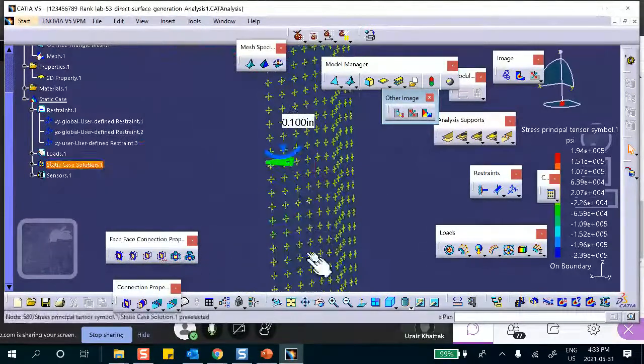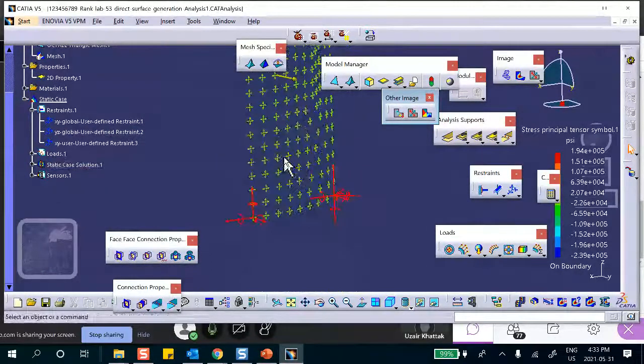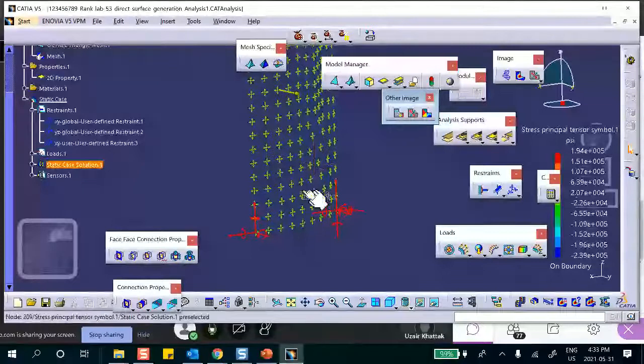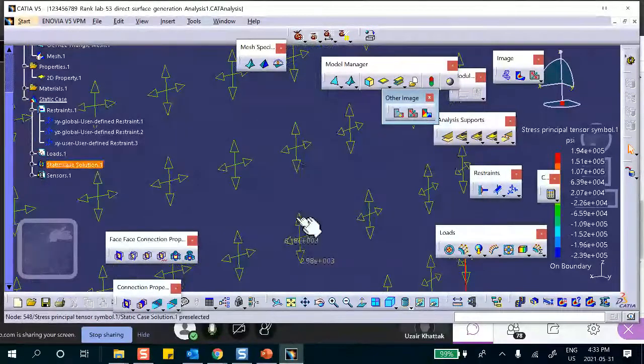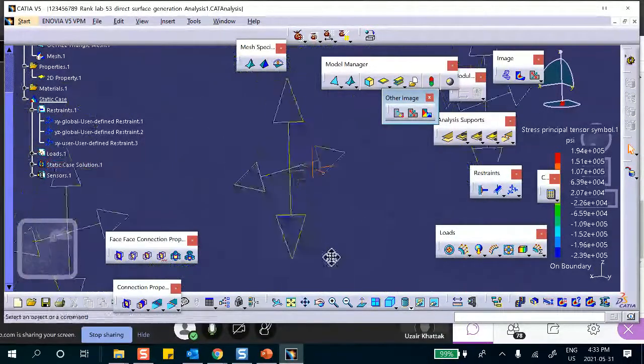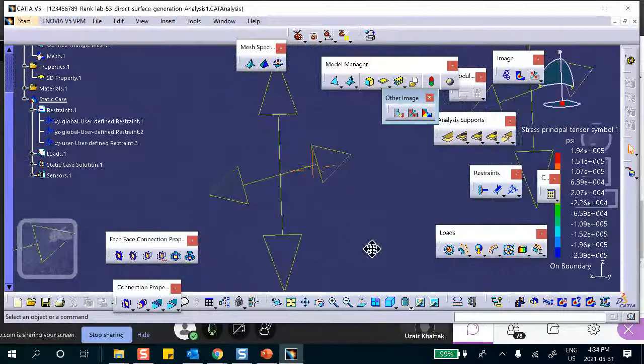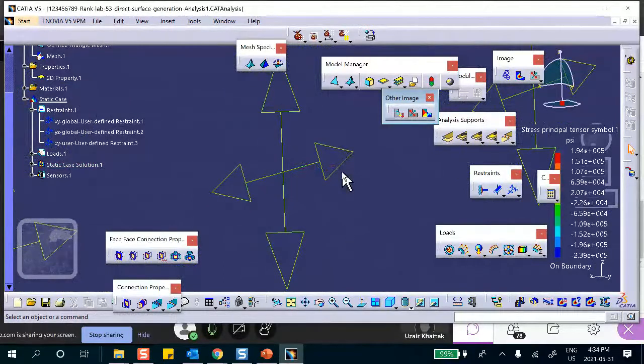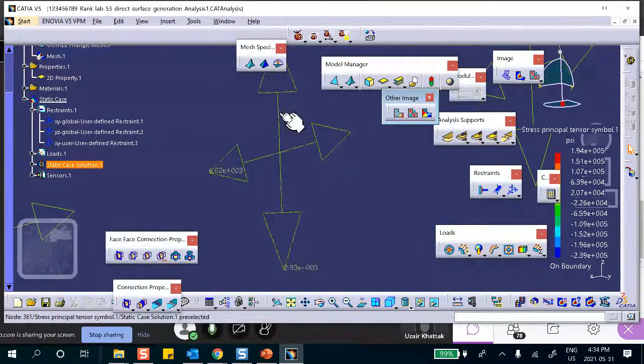If you stay away from it, you go to the middle of the tank, down here, this is the middle of the tank, and you put the cursor on it, look at what it says. Okay, let me look at the numbers. This is the hoop stress, better be 6,000. 6,020. Look, it says right there. This is the axial one, it better be 3,000. Look, down below, 2,930.